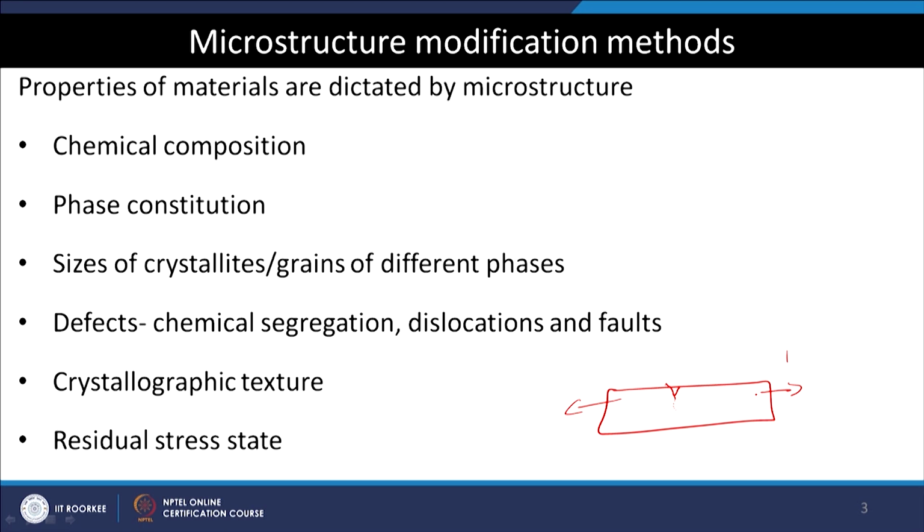there is a critical load at which this crack starts to progress inside and we can see the failure. Now, for example, we have the same situation, where we already have a residual stress acting on the top surface. For example, compressive residual stress acting on the top surface, and that is a very thin region. This is the top surface, and the remaining portion feels a little bit of tensile stress to have stability for the shape.